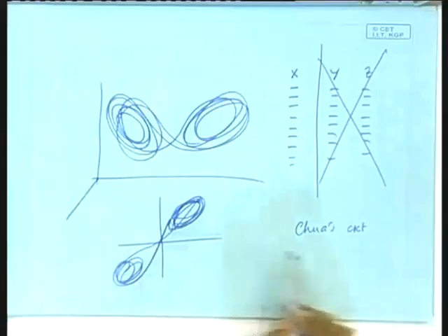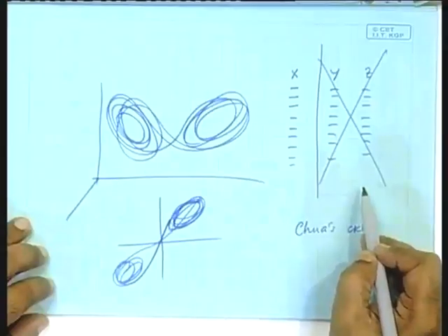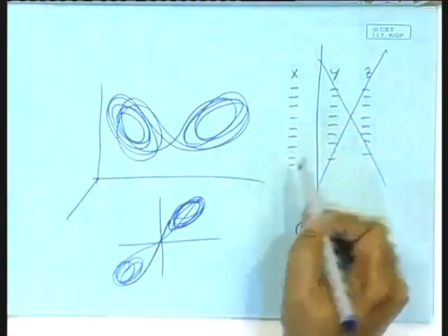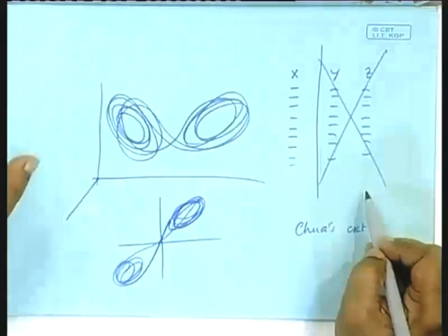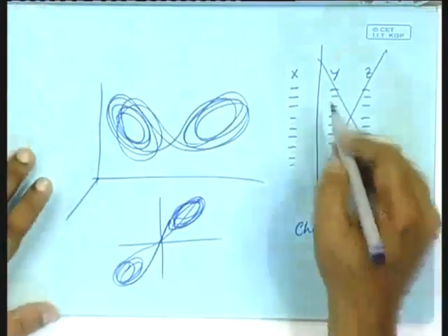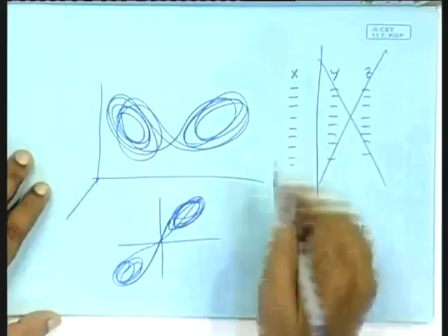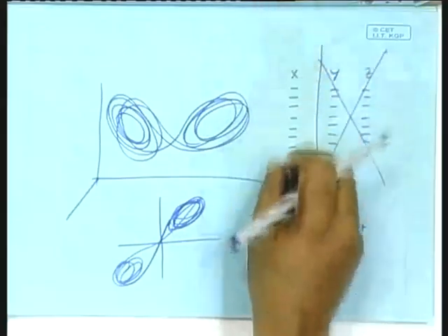This is actually a 3-dimensional system. There are 2 capacitors, capacitor voltages, and 1 inductor, inductor current. So, these are x, y and z. So, x variable Vc1, y variable Vc2, z variable IL, there is only one L. Generate that and eliminate that, keep only this. Now, give a suitably chosen tau, the delay length. Suitably chosen means you might play with it, no problem. I take 10 steps as my tau, let us see what happens. Take 50 steps, let us see what happens. Take 100 steps, let us see what happens.